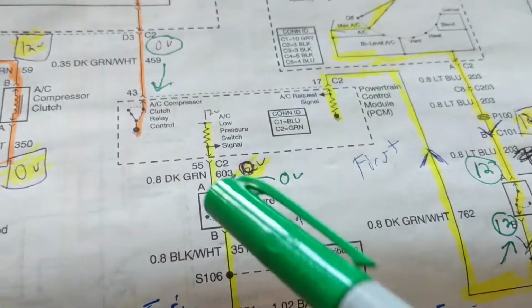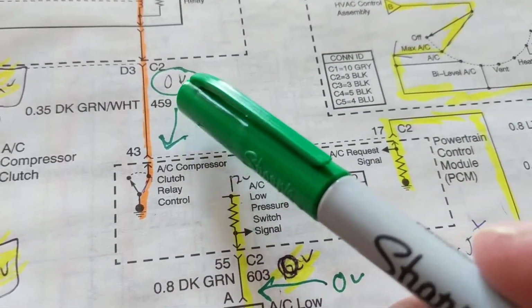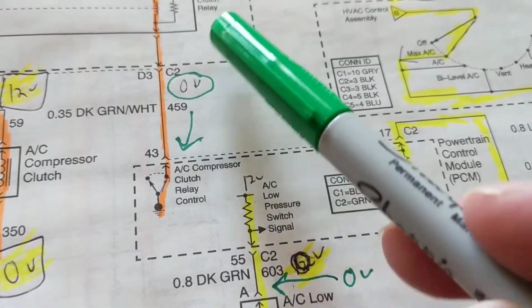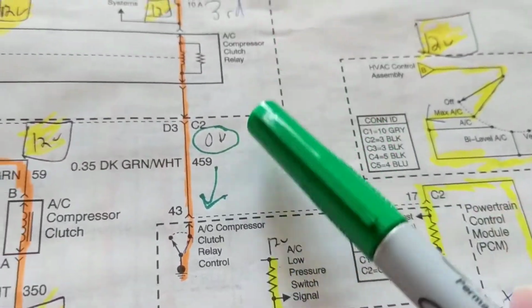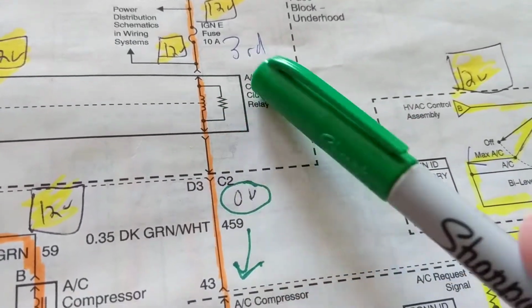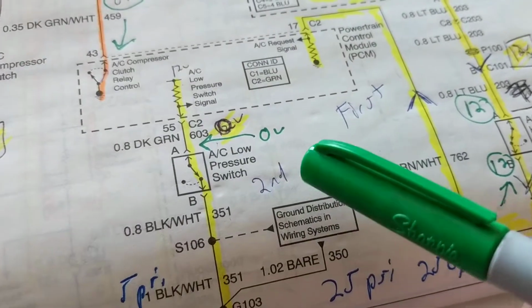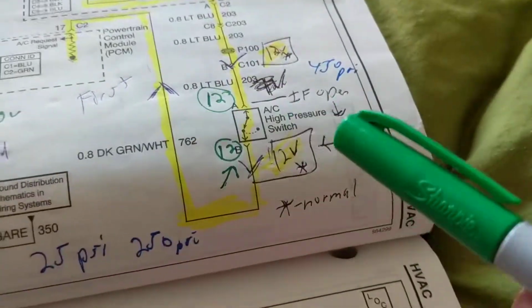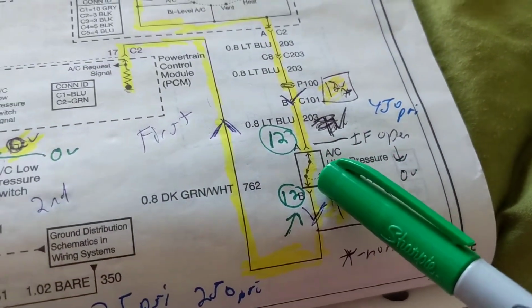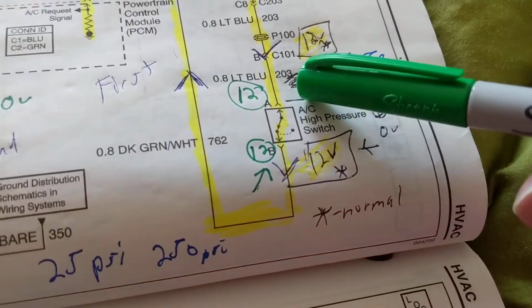What do I recommend? Again, I go over here and I will show you in the relay, hopefully when I get enough views, how to measure it. 0 volts, I measure 12 volts here, 12 volts here, that means 0 current going through here. This is open. What's my next procedure? I want to make sure this is closed. This is 12 volts on this side.